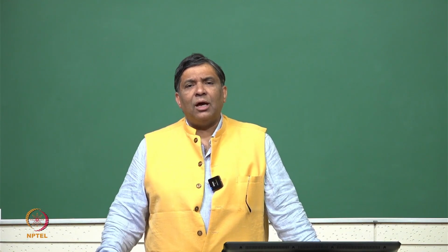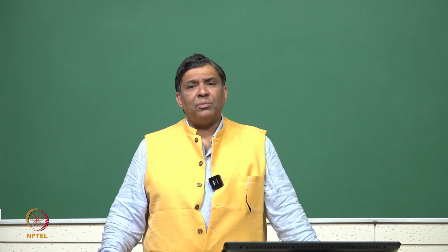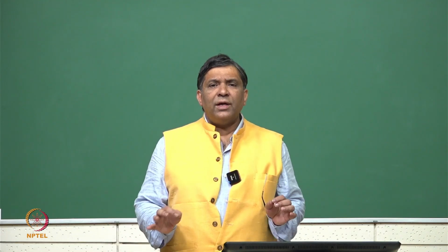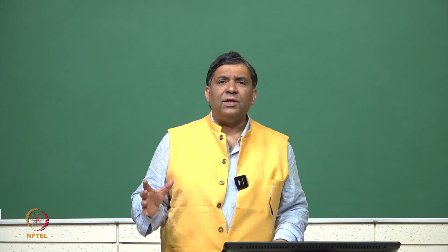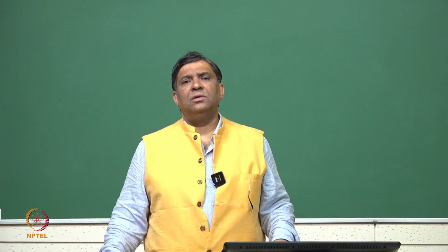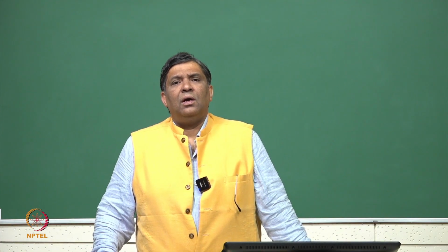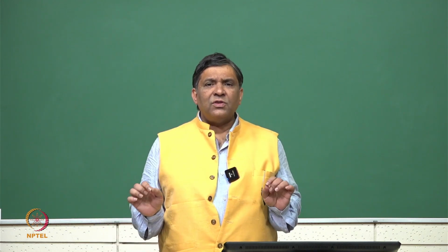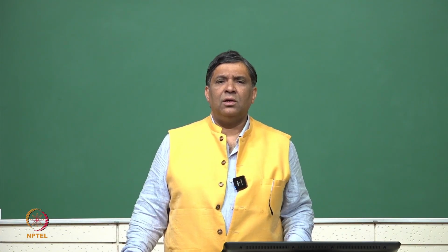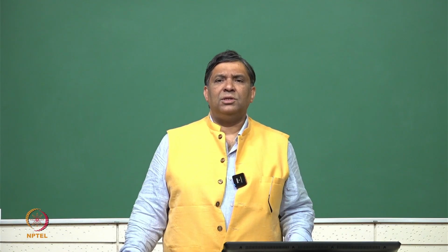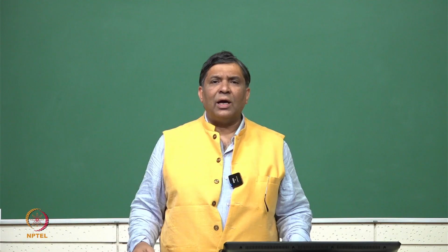And then we discussed about efficiency of a thermionic generator, how one can calculate the efficiency and what are the factors that decide the efficiency of a thermionic converter or thermionic generator. And then we discussed specifically one important thing, that is space charge effect in a thermionic generator, which is basically about the electron flow from emitter to collector.